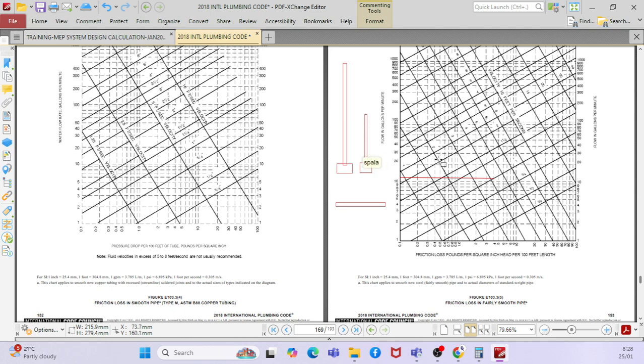So that is why whenever you go to FCU, what will happen? Say you have an FCU with a flow rate of 100 liters per second, and 50 Pascal is the FCU pressure drop. When you actually install it, when you put a motorized damper, a damper, everything, assume your pressure drop is 75 actual at site, but your FCU is selected for 50 Pascal. So what will happen at the site? You will not get the proper flow rate at the discharge or the diffuser. So that is why you have to properly calculate the pressure drop here.